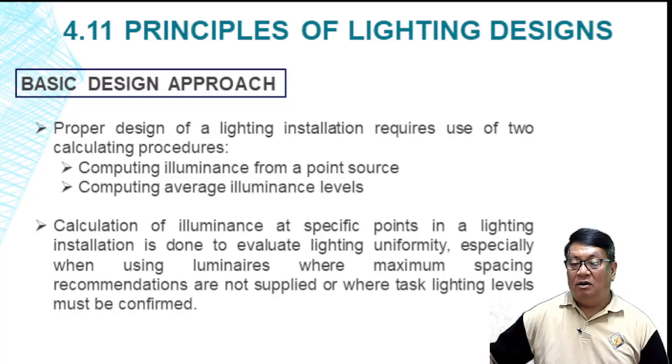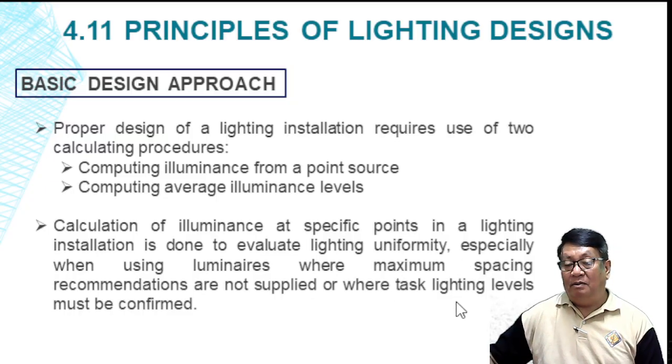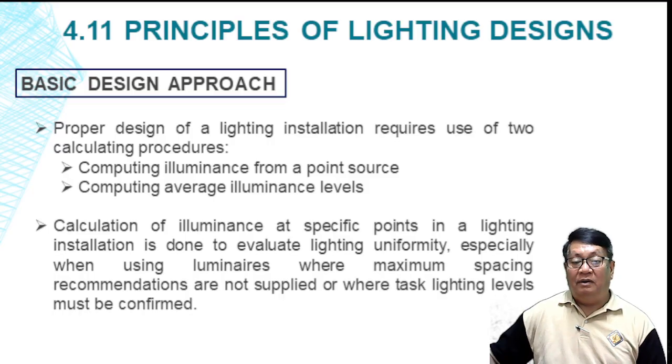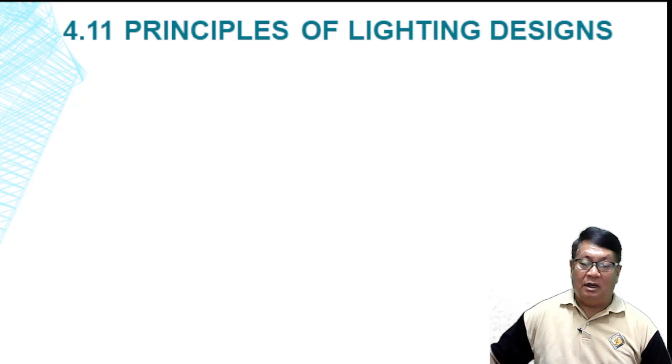Okay, so this is the calculation of illuminance at specific points in a lighting installation, no? It is done to evaluate lighting uniformity, especially when using luminaires where maximum spacing recommendations are not supplied or where task lighting levels must be confirmed.